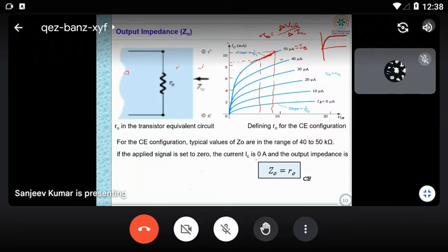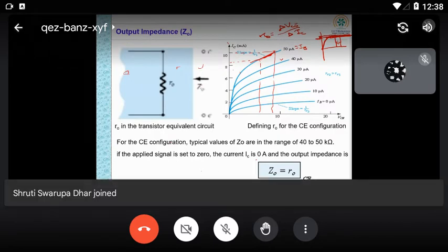So now if you see this, voltage may vary, but current will be very small, no? So this will be zero. Now if I'm taking change in voltage by change in current, because this is a constant, for an amplifier I need this type of curve, in the active region it should look like this. So then this change in IC current will be minimum or zero. So that's why ideally it should be infinite.